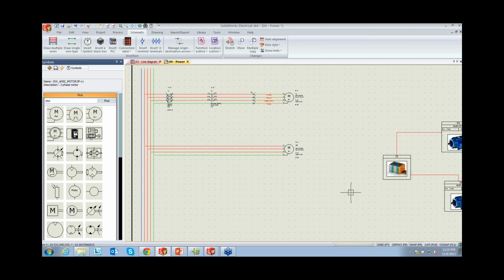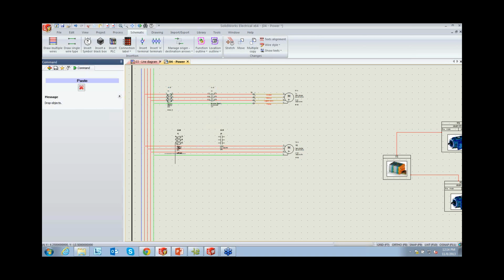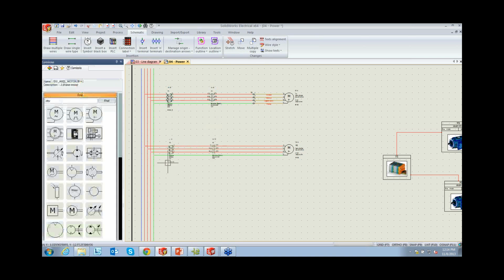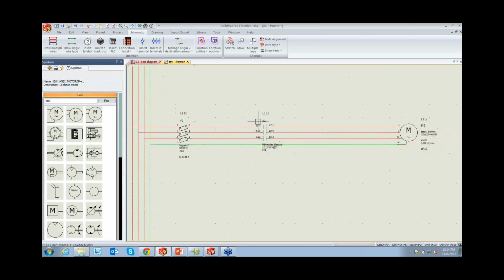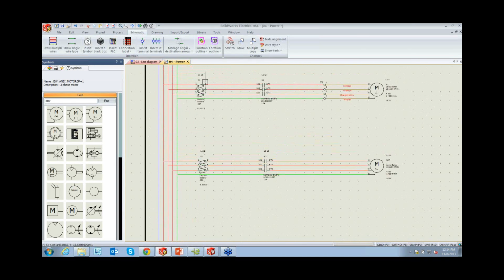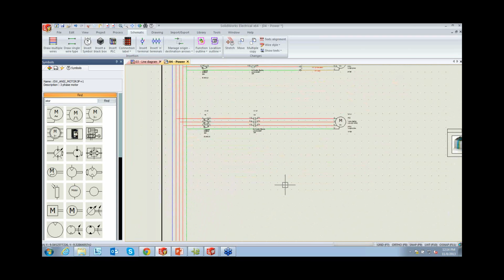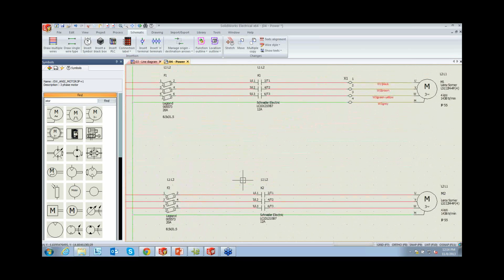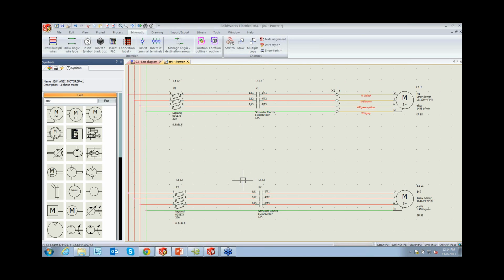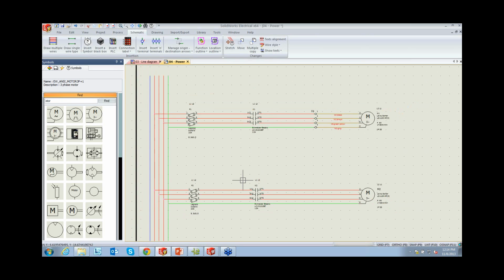So I've got this in here. I've put my motor in. Like our designers, even I like to copy paste. And when you do that, you see that it created new device designations or marks, so I don't have to worry about any duplications in this process. So basically, if you zoom in there, you would see that you copied F1 and K1, and it is now F2 and K2, and it also broke those lines and added that into those connections. Yes, now they are intelligent connections. They aren't just lines. They are wires with electrical information. So you don't have to trim them or anything like that. That is really great. Nothing of that nature is required.